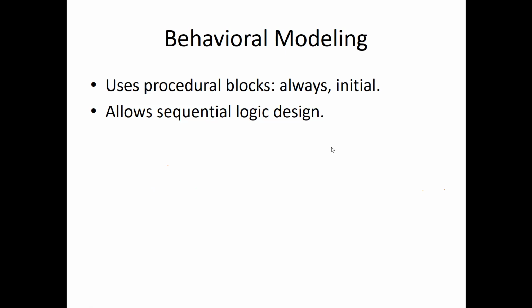Now we go for behavior modeling. Behavior modeling describes how the system behaves over time rather than its structure. We use the always block for repetitive logic and the initial block for one-time setups. For example, suppose we write a D flip-flop with reset. How can we write it here? This is also one example of behavior modeling, using a D flip-flop.